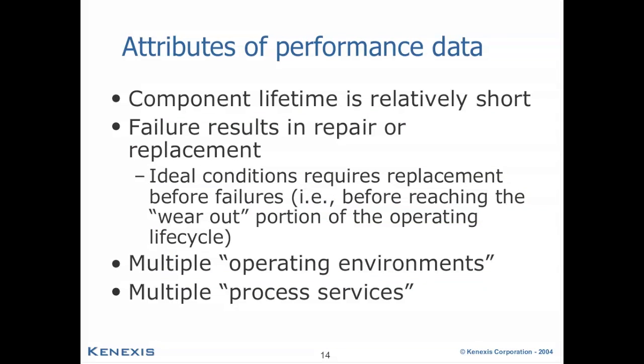With performance data, as mentioned, the component lifetime will be relatively short compared to that of the data that you may be able to establish within a test. The failure result is typically expected to result in a repair or replacement, and ideally the device will be replaced before the component fails, before it reaches the wear-out portion of the operating life cycle. And you may have to take special consideration for multiple operating environments and process services.